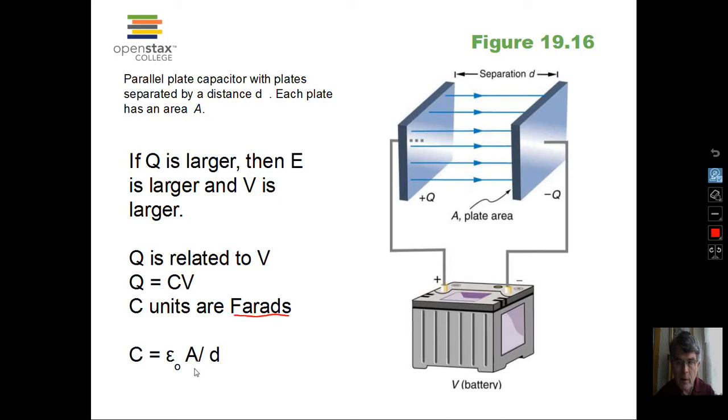For the parallel plates, it's a case of the area and the distance between the two plates that make a difference. A good exercise is to calculate the area and then the length of one side if the capacitance is 1 farad, and let's choose 1 millimeter for the distance between the two plates. You'll be a little bit surprised at how large this parallel plate capacitor has to be. And there's a solution for this problem, but let's continue.